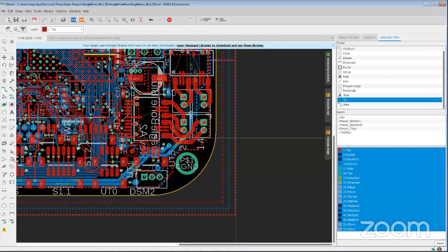How can you invert your PCB for UV exposure? I don't think we have something like that right now. What you have to do, the best way to get that inversion, is you can export the board as an image using CAM to image is one option, and then in Paint invert the colors, or whatever graphics program you want to use. That's one option.